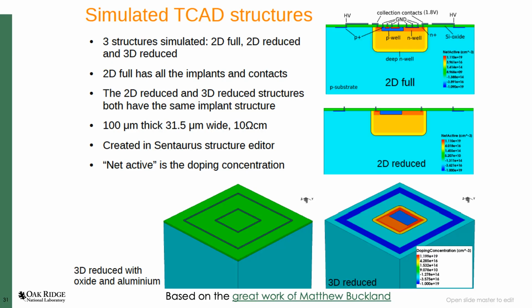For example, for Tower Jazz, which I will show next week, we didn't care so much about the circuitry implemented in the big P well. We just assumed we were pretty well shielded from the substrate. We have this big well, and everything is inside other wells.